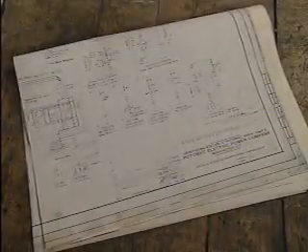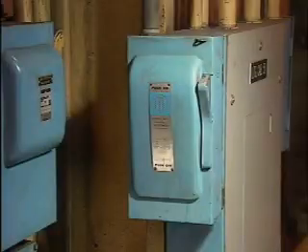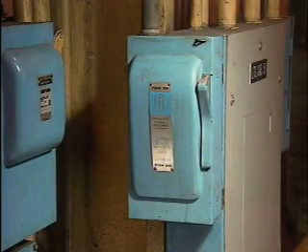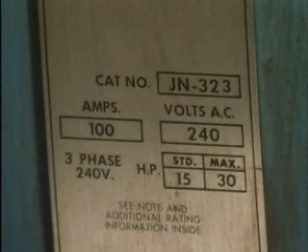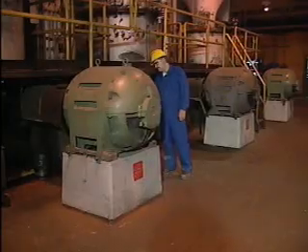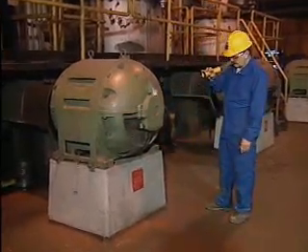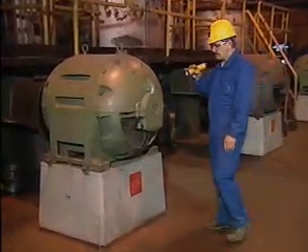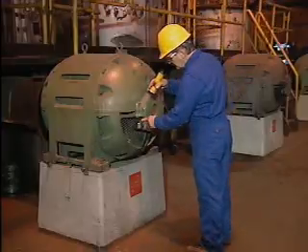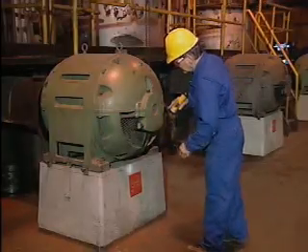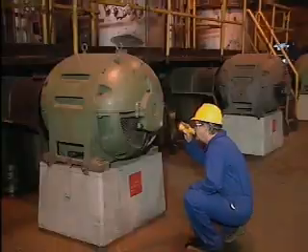One way to get information about the nominal voltage for a circuit or a piece of equipment is from an electrical diagram. Another way is to read the information on the equipment's nameplate, if one is available. Being able to determine the nominal voltage level of a circuit or a piece of equipment is an important part of working safely because it helps you determine the types of protective gear you'll need.